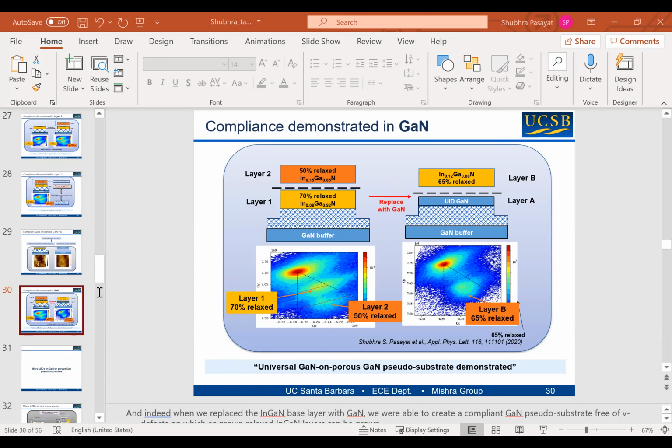Okay, Lei Wang says, can you talk about the comparison between this technology and the current micro LED used in AR/VR for the cost performance? Okay, so currently in AR/VR, I think for blue and green it's InGaN, but for red, AlGaInP micro LEDs are used.